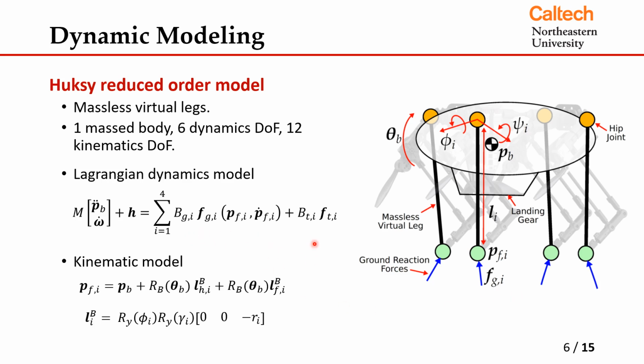And since we have thrusters, we also have the thruster components attached at the legs. We modeled it to be implemented at the leg end position, but it can be anywhere within the leg. So it follows the kinematic model here, and the ground force formulations can be calculated from this leg end position in the inertial frame over here.